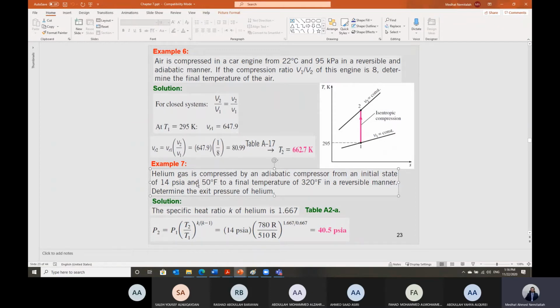It is used in car tires. Usually when you go to set the car tire pressure, it should be about 35 psi. 1 psi is about 0.07 bar, so 35 psi, the car tire pressure, is about 2 bar. So the pressure of the air inside the car tire is about 2 bar. This is psi, pound per square inch, and the temperature is given in Fahrenheit.